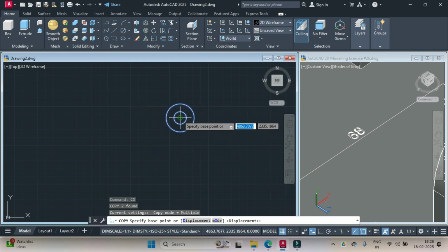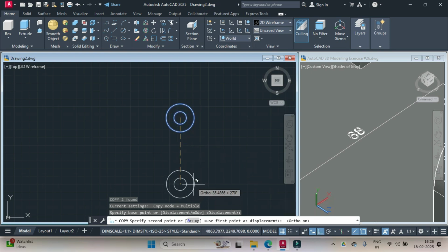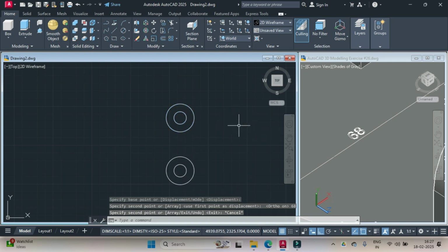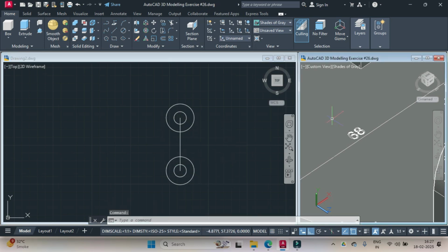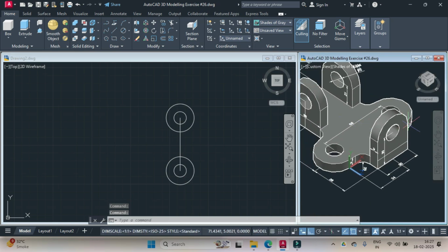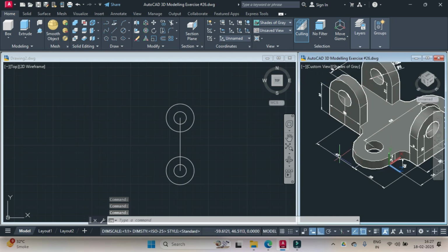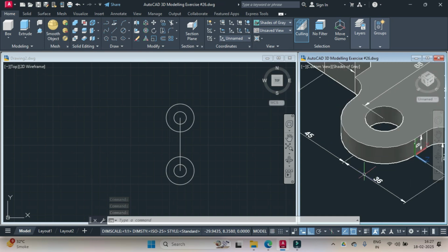This is the center point. Ortho turn on. Distance is 68. Press enter. Again press escape to come out of this. L for line. Draw a referential line from center point of this to center point of this and press enter. Now we'll copy that line to the left, and if you see in this drawing it is 45 units and to the right it is 36 units.